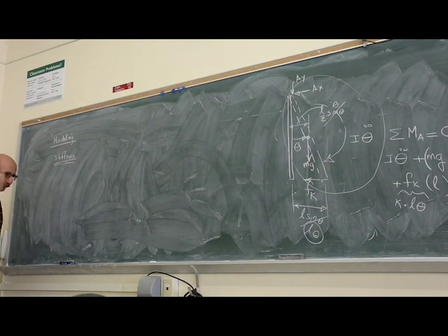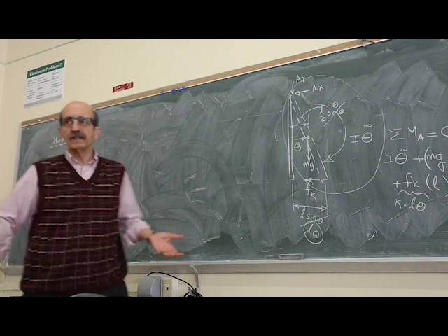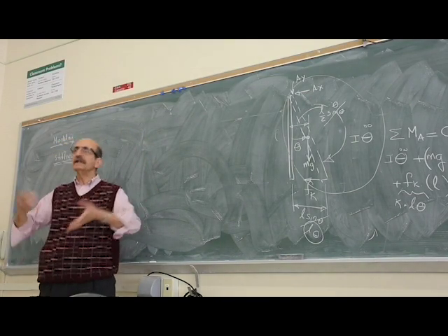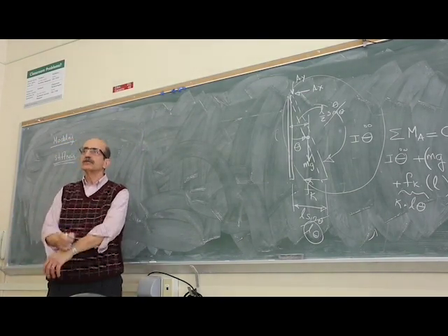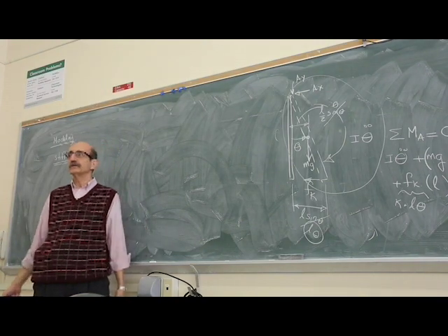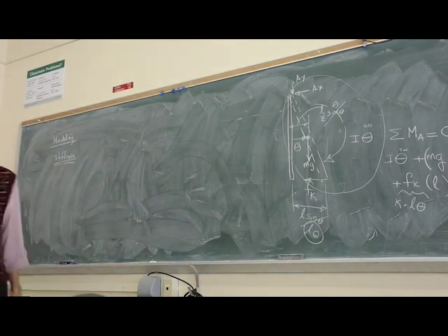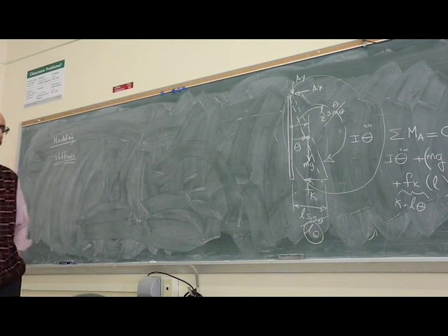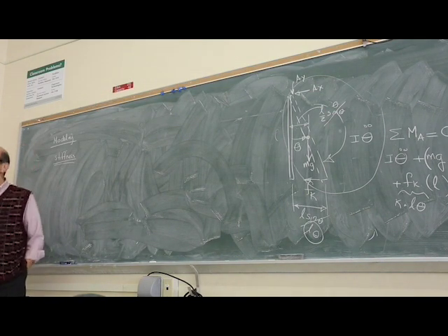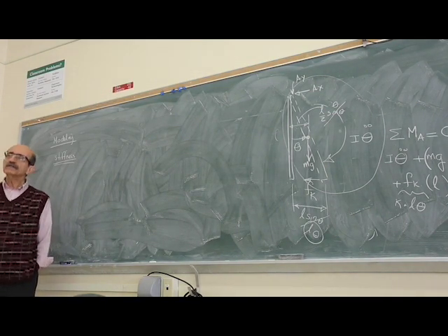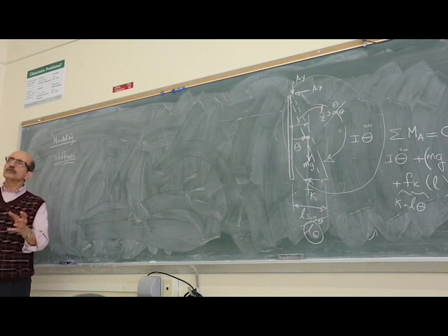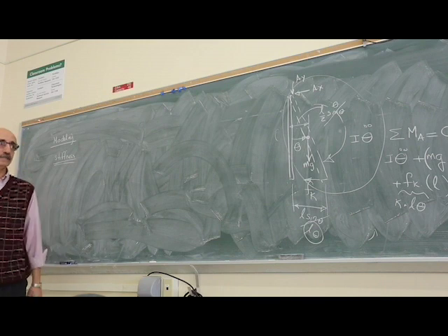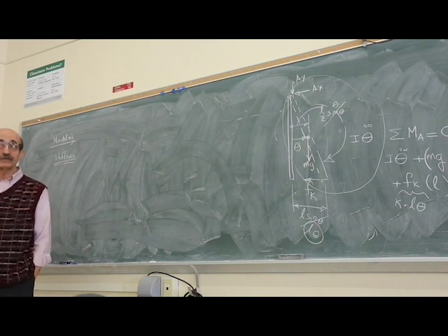As I said, every structure is made of many pieces. You've already seen that in statics. You may be dealing with a truss that is made of many axially loaded members, two force members, or a frame that is made of several pieces that each can be a beam element or a truss element. So when you have a complex case like that, each of those pieces has a stiffness, and can be represented by a spring, based on the definition of the spring that I introduced.